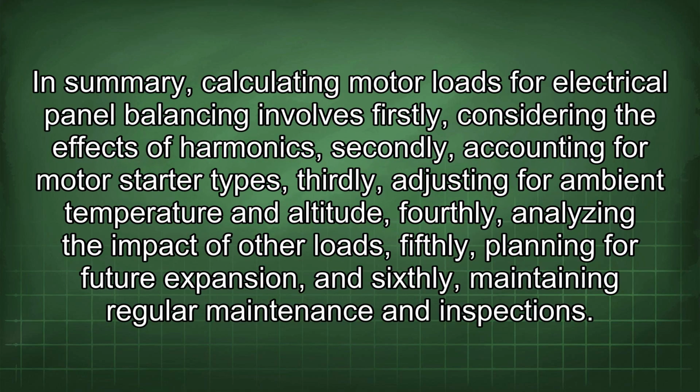In summary, calculating motor loads for electrical power balancing involves, firstly, considering the effects of harmonics, secondly, accounting for motor starter types, thirdly, adjusting for ambient temperature and altitude, fourthly, analyzing the impact of other loads, fifthly, planning for future expansion, and sixthly, maintaining regular maintenance and inspections.